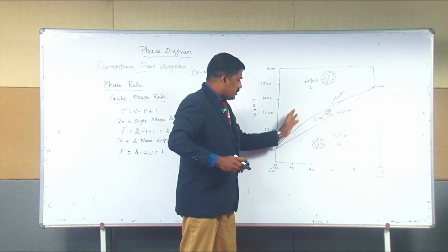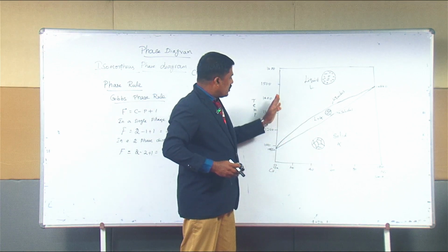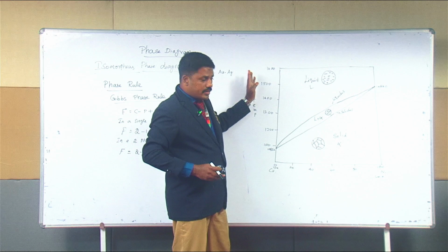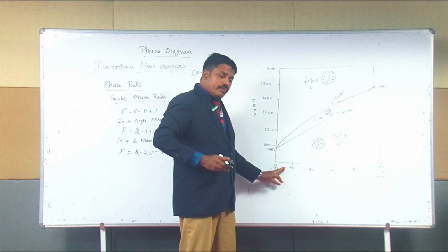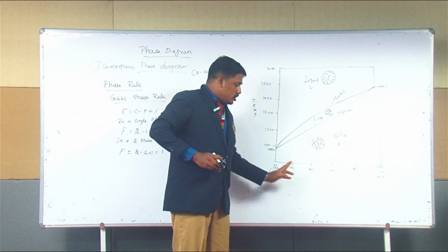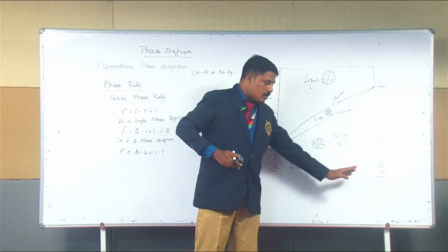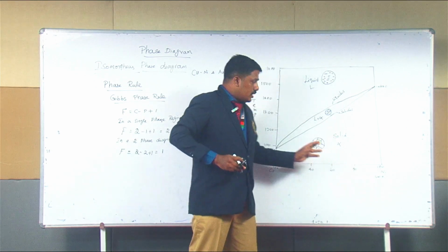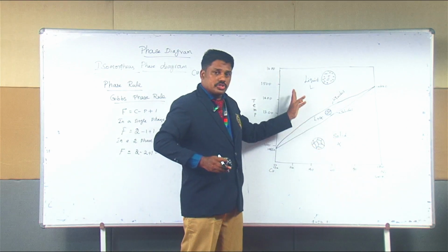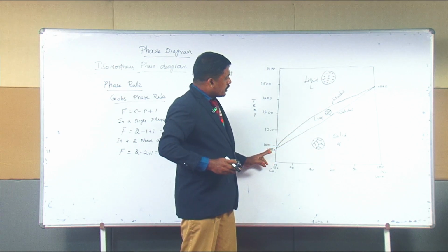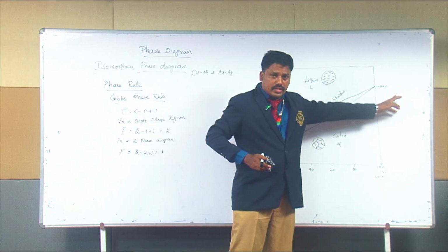When we raise the temperature from 0 to 1600 degrees Celsius and change the composition, the amount of copper and nickel, the melting point temperature slowly varies from 1085 degrees Celsius to 1483 degrees Celsius.